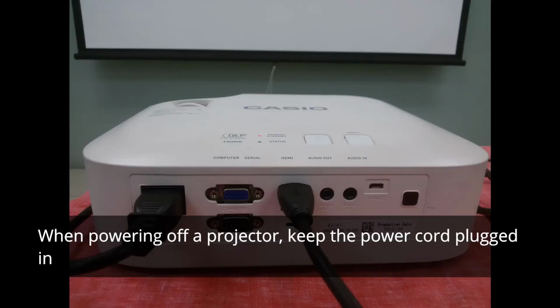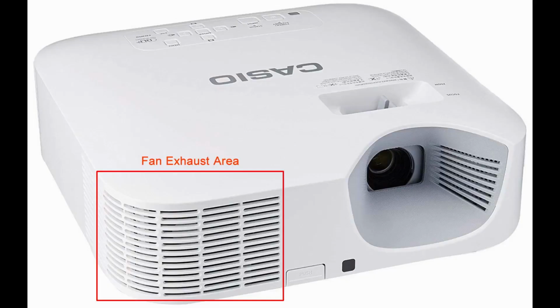When powering off a projector, keep the power cord plugged in until all the fans have stopped. It will run the fans during the powering down in order to cool the internal components of the projector. This could take a minute or more depending on what the internal temperature of the projector is at the time.